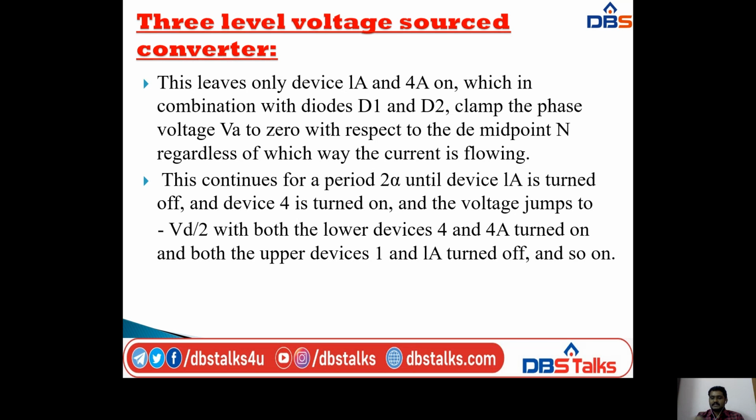The two capacitors are connected to midpoint N. So with respect to the DC midpoint N, regardless of which way the current is flowing, that will show on the second waveform. And this continues for a period of 2 alpha.